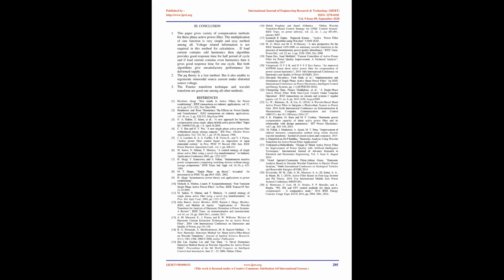One of the disadvantages of the Fourier transform is that the points observed in an observation window should be proportional to the number of samples per time. If the points in the observation window are not in proportion with the number of samples per period, it leads to inaccuracy in the extraction. The wavelet transform method helps to minimize the above demerit. Wavelet analysis is a new method in applied mathematics. The voltage and current quantities are transferred to the time and frequency axis using the complex wavelet with the help of scaling and translation factors.